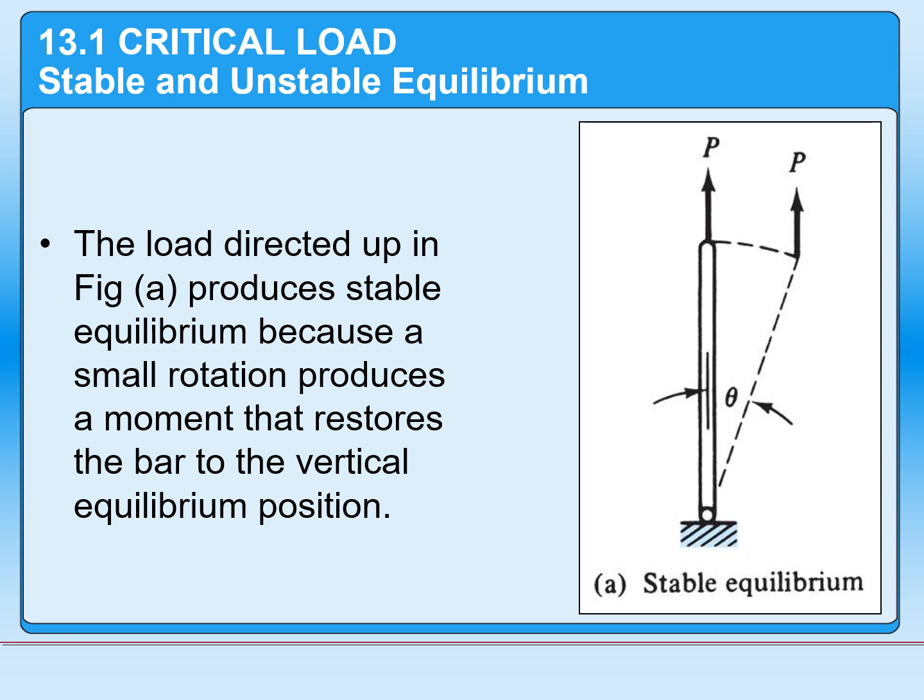The reason why configuration A is considered stable is the load is such that if we make small changes, in this case small changes in rotation, since it's a hinged bar, the moment that's going to be created is actually going to tend to restore the bar back to its initial condition. As a result, small changes have very little effect on this overall structure, and it's somewhat self-correcting.